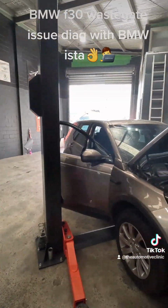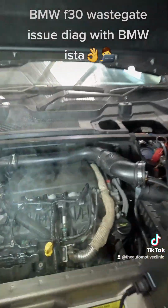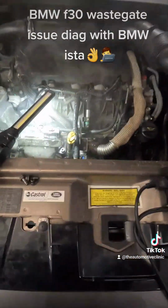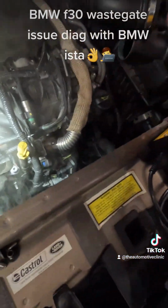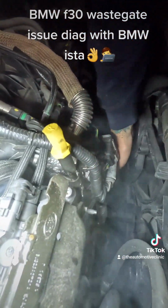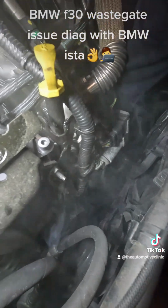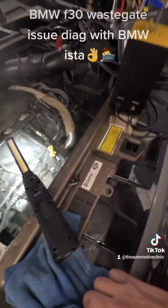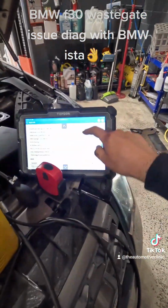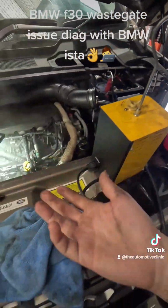Good afternoon everyone. Today we have a Land Rover Discovery in with a boost leak. Now this vehicle has had ongoing DPF issues. I'm not going to be able to show where this is, but it is on this main boost hose down here. So if you see where my hand is here, right at the back we've got a large boost leak. There is a split in that boost hose. So this leak has caused a MAP sensor fault, namely this one, P006A, and it has caused ongoing DPF issues.